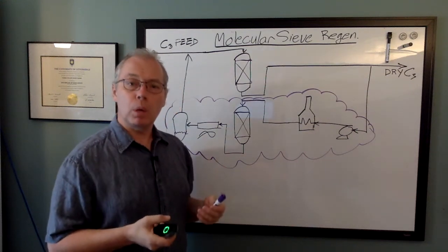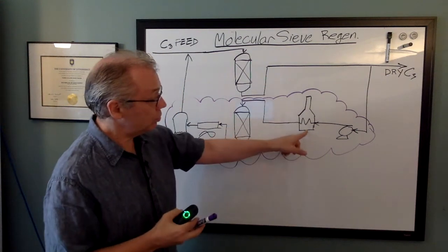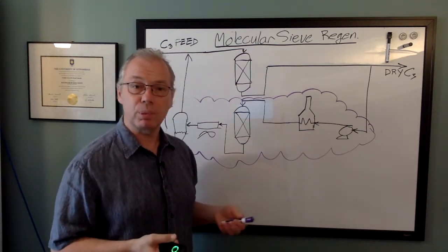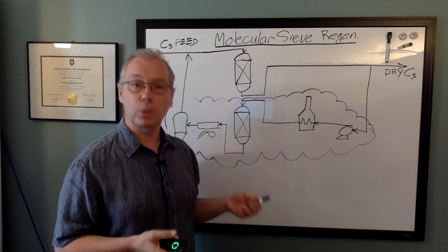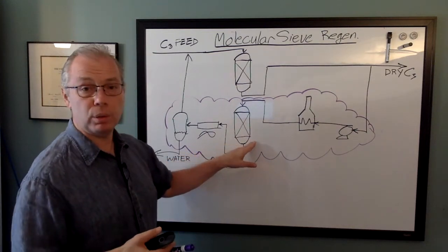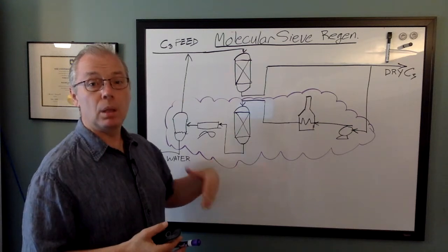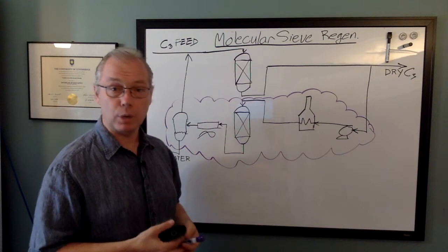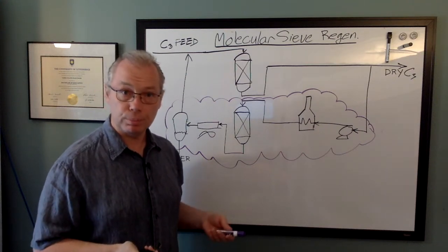Then I'll apply the model to the furnace to see how the light-off process produces a large flow disturbance, and then we'll take a look at the plug flow through the dehydration bed to demonstrate how it's warmed up and de-inventoried of liquid hydrocarbon during regeneration.